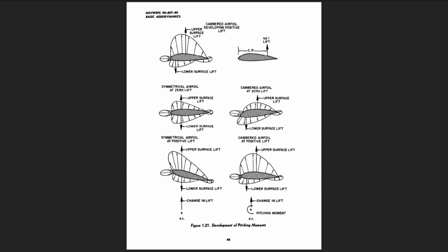It should be noted that the symmetrical airfoil at zero lift has no pitching moment about the aerodynamic center because the upper and lower surface lifts act along the same vertical line. An increase in lift on the symmetrical airfoil produces no change in this situation, and the center of pressure remains fixed at the aerodynamic center.